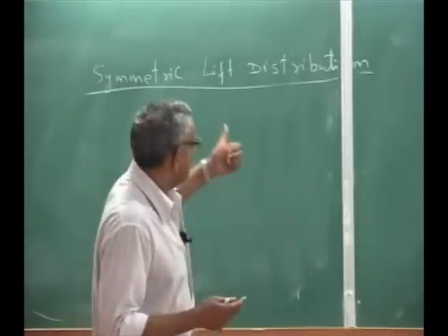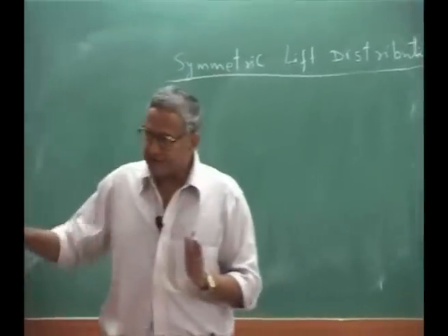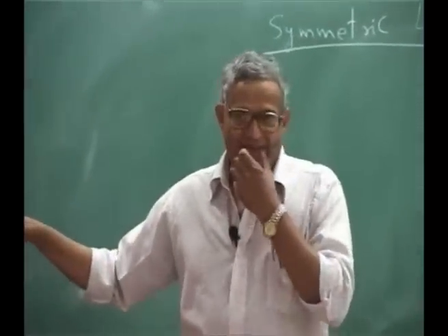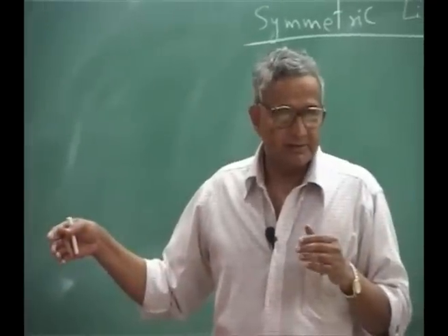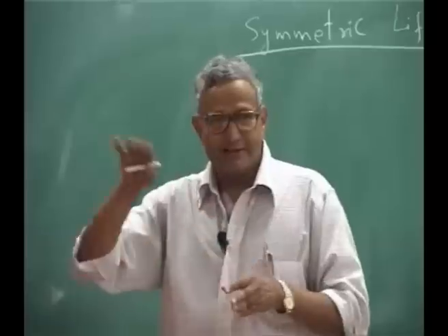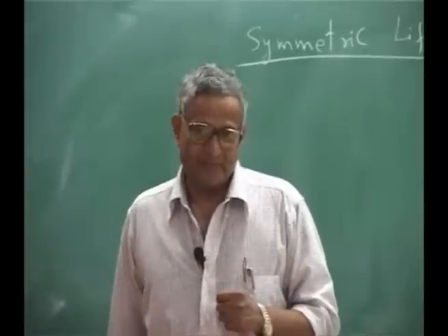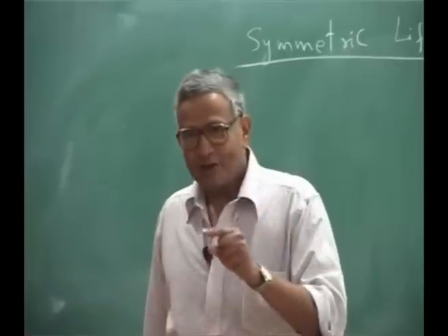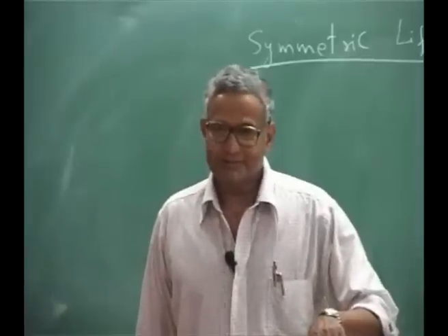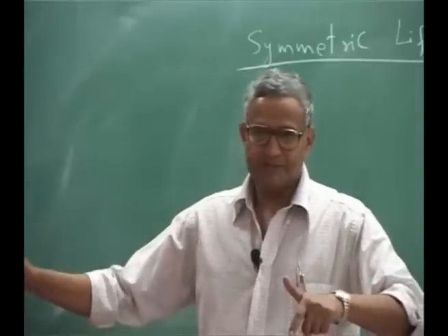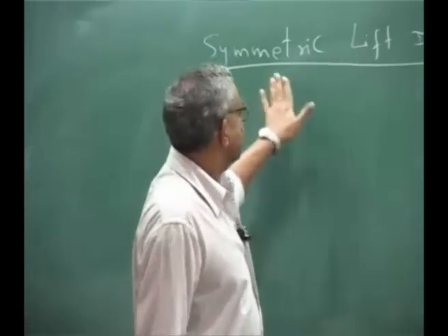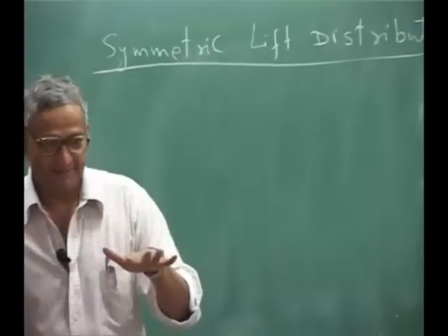Okay. So in this problem, if you consider the aircraft wing as a rigid one, you will get one load distribution. The moment you consider the aircraft wing is flexible in twist, you will get a different load distribution. And then you need to get the new load distribution due to the deformation of the wing and the flight condition. So the flight condition is, we say, symmetric flight.